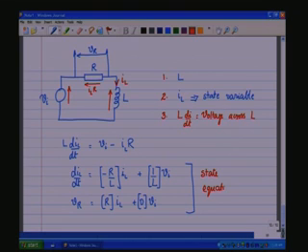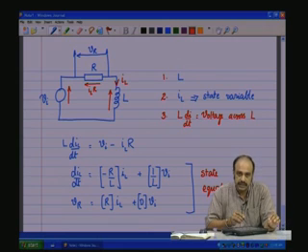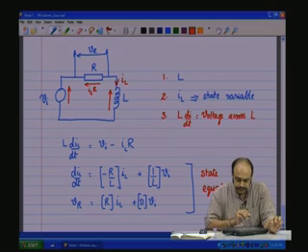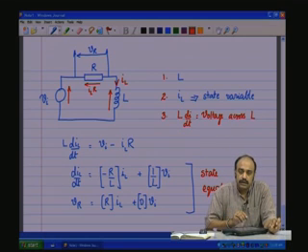You see, it is so simple. Actually, whatever be the complexity of the circuit, you just have to follow these three steps. That is, step 1, identify the energy storing elements. Step 2, identify the state variables associated with these energy storing elements. Step 3, with no particular order, starting at any particular energy storing element, the equation describing its dynamic behavior can be put down, and then followed by the equation describing the dynamic behavior of all other energy storing elements in the circuit. So, that is the method that we will be following.